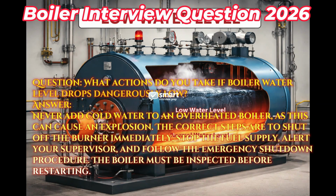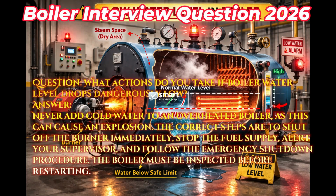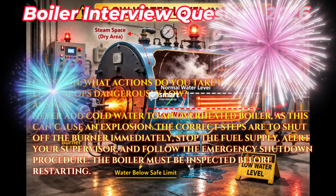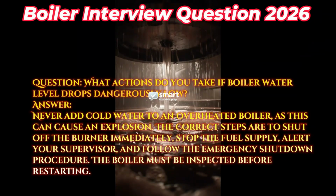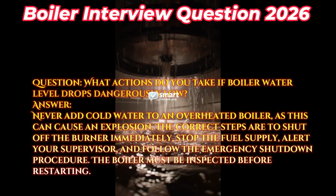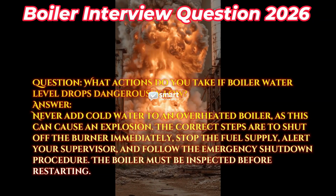Question: what actions do you take if boiler water level drops dangerously low? Answer: never add cold water to an overheated boiler, as this can cause an explosion. The correct steps are to shut off the burner immediately, stop the fuel supply, alert your supervisor, and follow the emergency shutdown procedure. The boiler must be inspected before restarting.